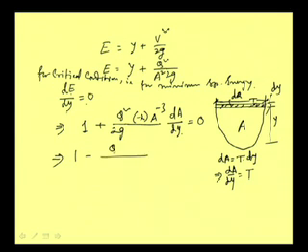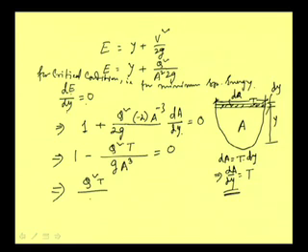So, we can write Q square by g, then this A to the power minus 3 means A cube I can write in the denominator, and this dA/dy, from here we can write, is equal to T. So, this is equal to 0. This leads us to one expression: Q square T by g A cube is equal to 1.